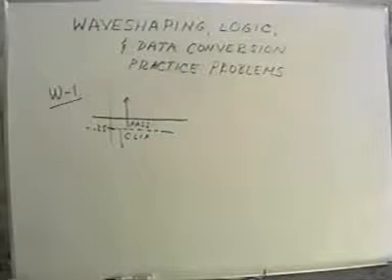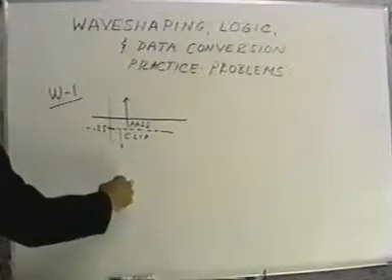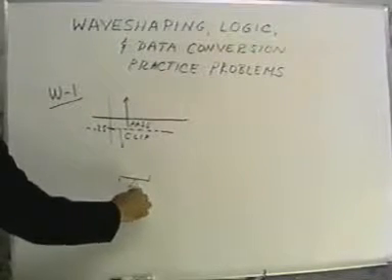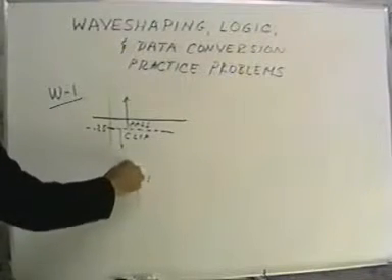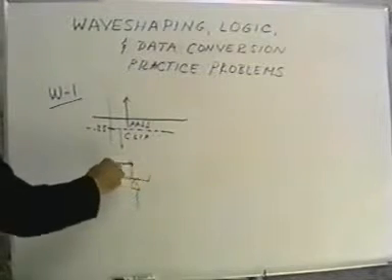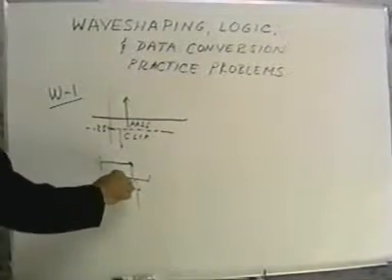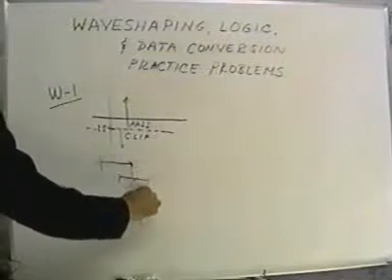The first part is to develop a precise minus 0.25 volt supply. And the way that is done, we would take a Zener diode and we would connect this end to ground, and now the Zener current will be flowing in this direction.